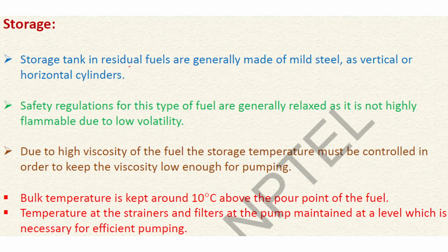Coming to the storage tank, residual fuels are generally stored in mild steel vertical and horizontal cylinders. Safety regulations for this type of fuel are generally relaxed, that is, it is not highly flammable due to low volatility. As they are heavier residual cuts, their volatility is not very high, so they are not very highly flammable. So they mainly come under the safer fuels.